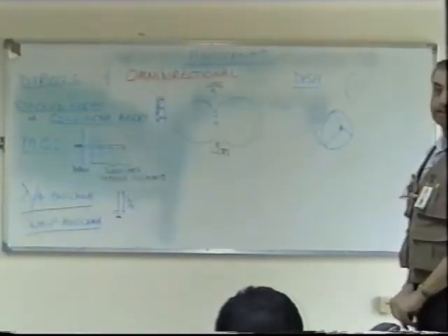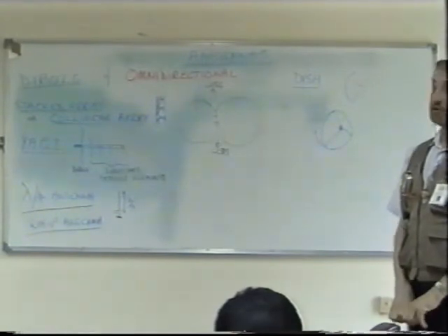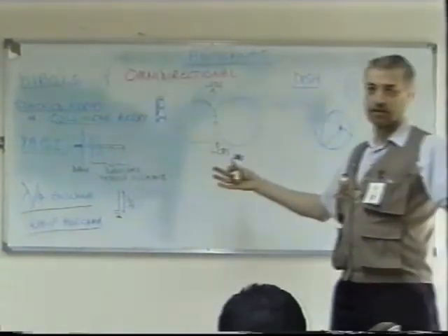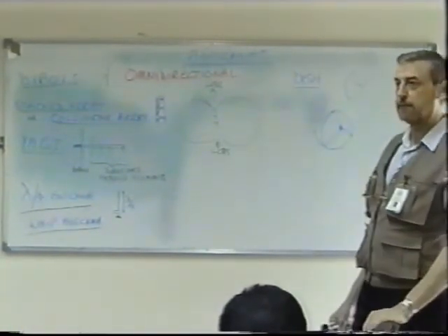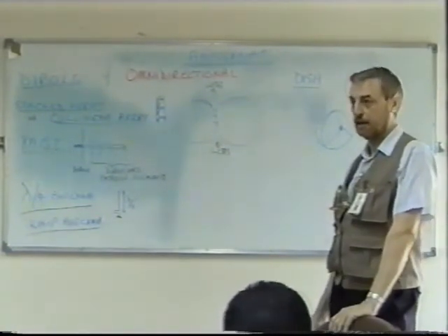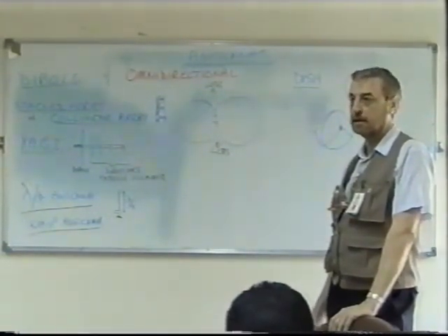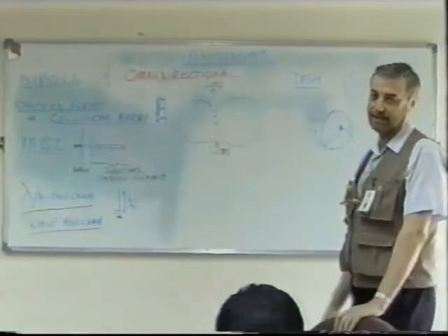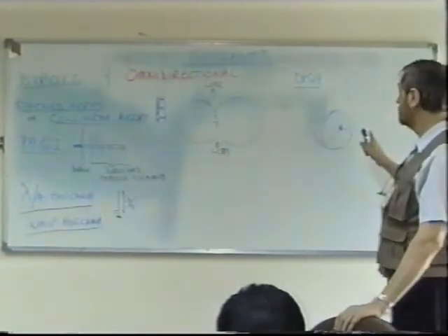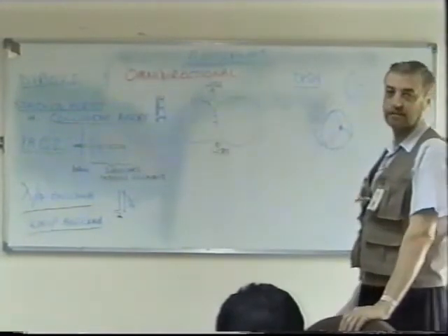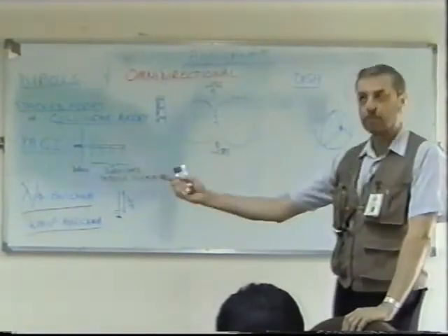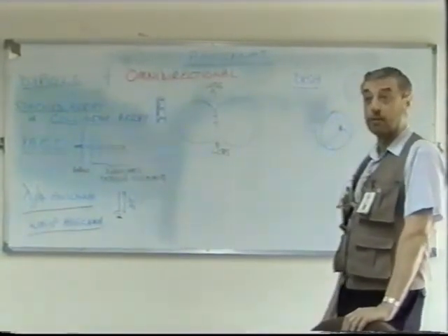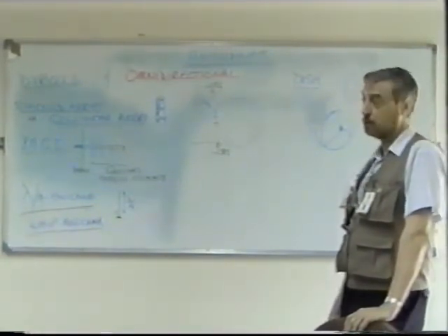We have to take the dish as the most directional antenna. It is the highest directional antenna, yes. It's not just for microwave, but in our use, it's microwave because of the size of the dish. We don't want it too big. When we use lower frequencies, it's better to use a different type of antenna. It's more practical. And don't forget, the dish is very directional. We don't necessarily want it directional. Sometimes we want it omnidirectional or close to it because we want it for mobile work. So you've got to choose the antenna according to what you want.